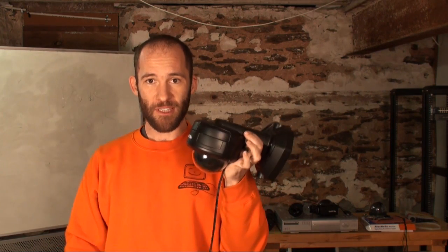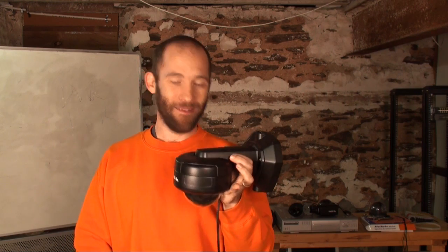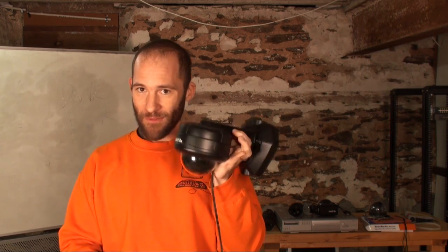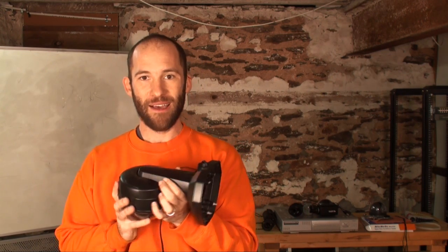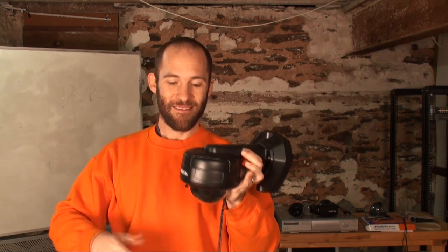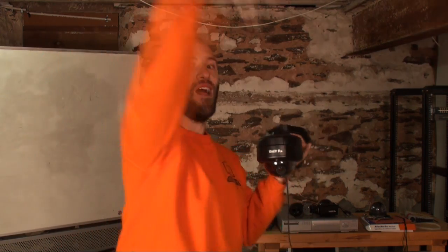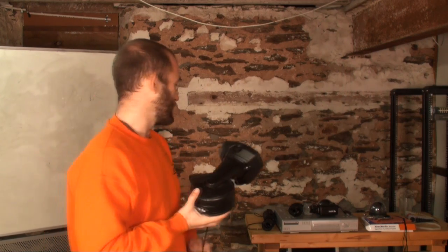One of the warnings that I'll give you with a vandal-proof dome is you can hit this vandal-proof dome with a sledgehammer and you're not going to hurt the camera. But it's only going to stay in the wall as well as you have mounted it. So I've seen people in the real world, they buy these very expensive vandal-proof dome cameras and then they mount it very poorly. Well, it's kind of like a piñata. Or not really a piñata, but you can hit it. The camera itself isn't going to be damaged, but if it goes flying into the next parking lot after you hit it, well, it's not very useful. So that's just one of the things to keep in mind with these vandal-proof domes. They're very, very hard, very, very stable, but if you don't mount them very well, they're still just basically easy to knock out and take out of commission.